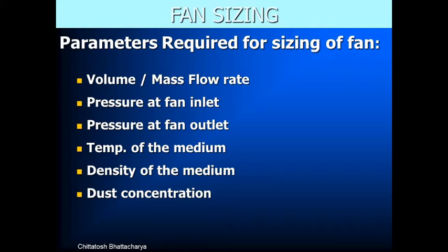So naturally the parameters we have to review for size selection of the fan are volume or mass flow rate, pressure at the fan inlet and the pressure at the fan outlet, temperature of the gaseous fluid, density of the medium, and how much is the dust concentration within the gaseous fluid. All this has to be taken care of for sizing.